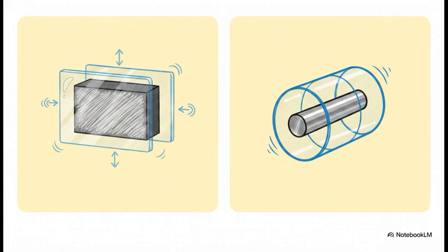But if you apply perpendicularity to a drilled hole or a cylindrical pin, and you use the diameter modifier in your feature control frame, you're no longer trapping a flat surface. You are controlling the feature's axis, trapping it inside a 3D tube-shaped cylindrical zone. And trapping a plane between 2 sheets of glass is fundamentally different than trapping an axis inside a virtual pipe.